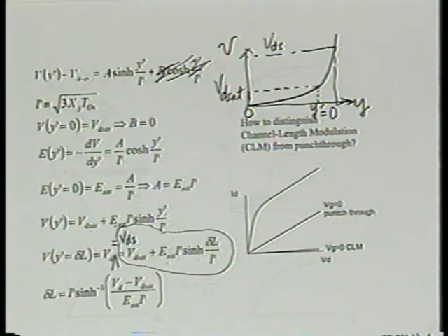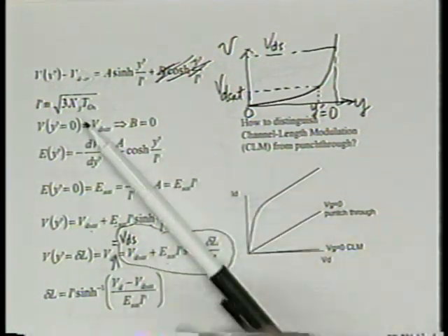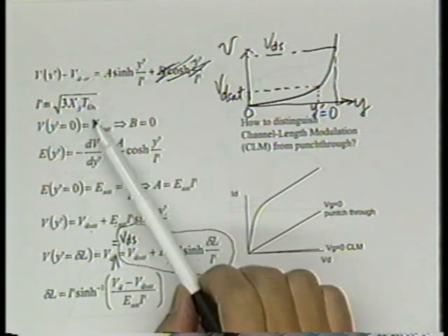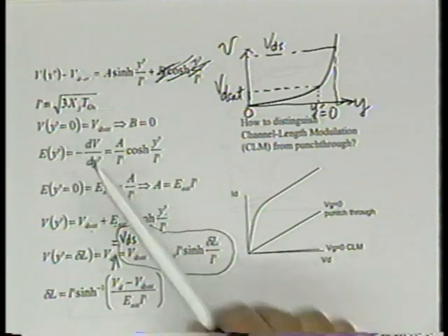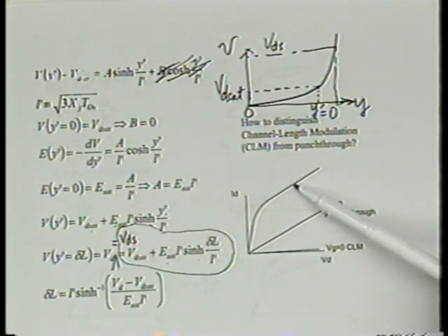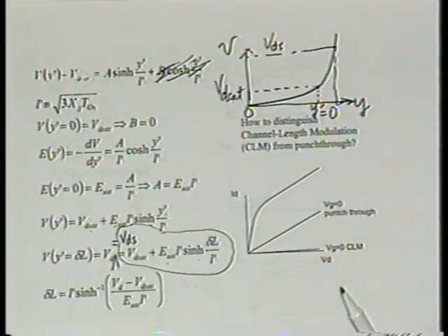So all makes sense. And by the way, this definitely is in agreement with what experimentally is known. For those of you that might know this, well, even if you don't know, you can probably believe me. If we make very short channel lengths today and still use the very thick oxide or deep junction, you can probably imagine IV curve will look like that, right? Kind of, won't show you a transistor curve. Looks more like a resistor. And that's exactly right. Okay?